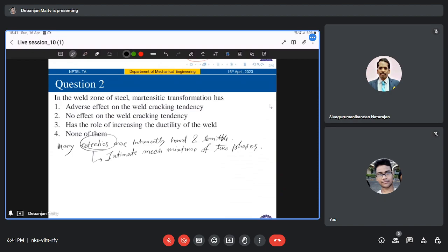So unfortunately, redissolving a eutectic requires temperatures that are well beyond what is normally considered reasonable for post-weld heat treatment, and that is into the solutionizing range where a single phase solid solution is formed above some solvus temperature.